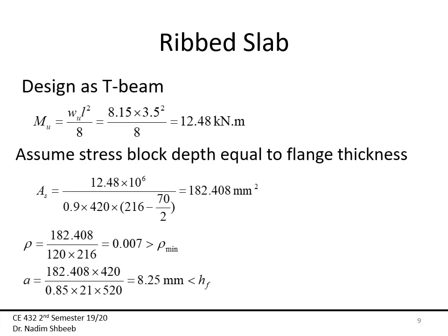Okay, now with the load figured out, we can calculate the ultimate moment, which is simply wL square over 8. Here you've noticed I've used the center line to center line distance, which is half of the columns, which is 0.25 and 0.25. Now, technically you could use the clear distance, which is about 3, but the difference in the moment is really not that much. I mean, it's about 9 point something, but still I went with the bigger one. Usually in the exam, I will specify to you which length to use as far as the calculation of the moment is concerned. So you really don't need to worry.